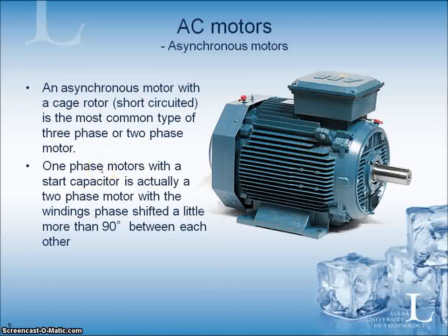1-phase motors with the start capacitor are actually 2-phase motors with the windings phase shifted a little more than 90 degrees between each other. So you sort of fool the motor so it can be run on only 1 phase, even if it is a 2-phase motor.